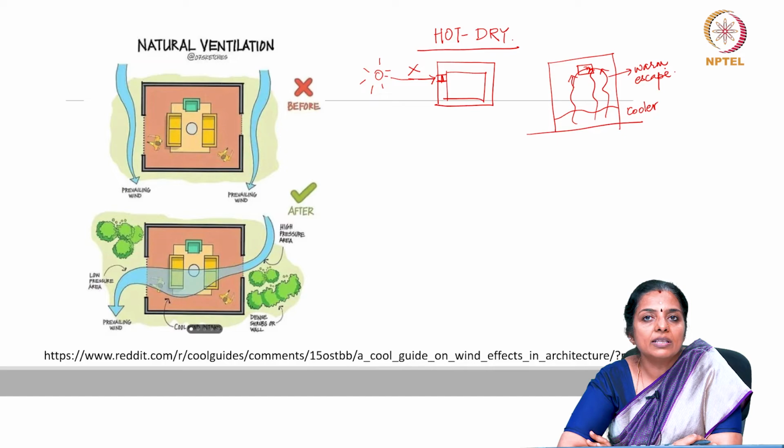Lower sill levels might therefore be preferable. In cold climates, fenestration should be large, unshaded but sealed. This would enable heat gain but reduce cool breezes. Fenestration location would be of little consequence.